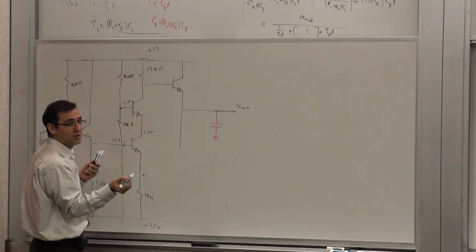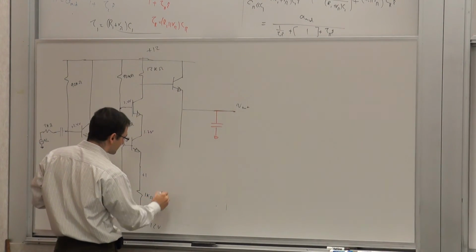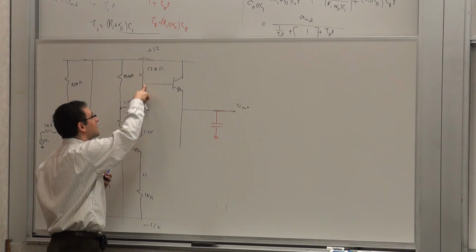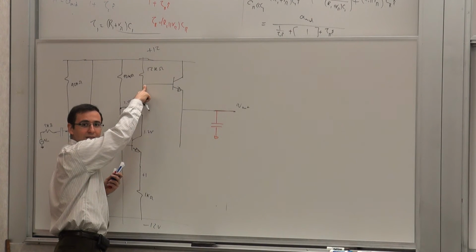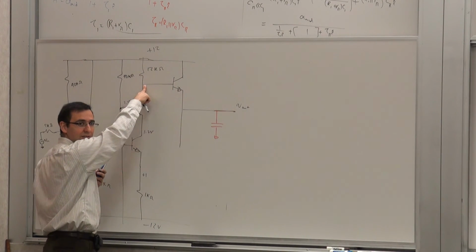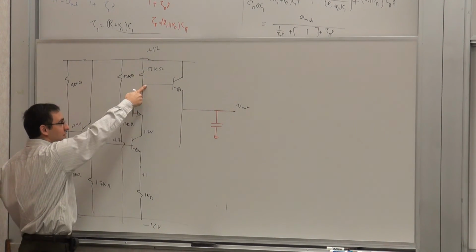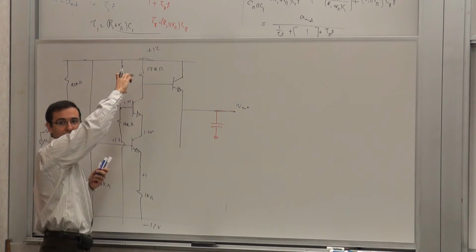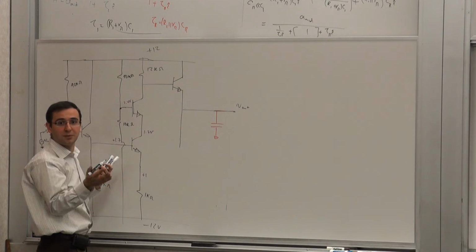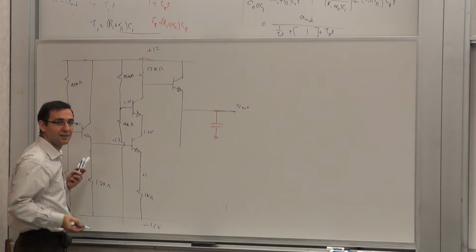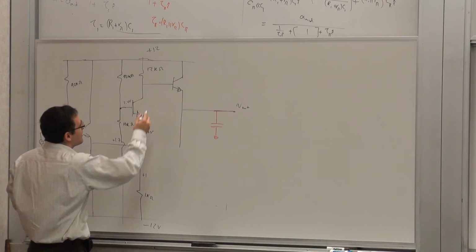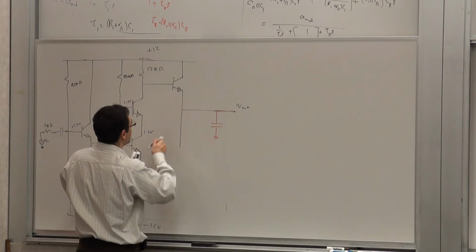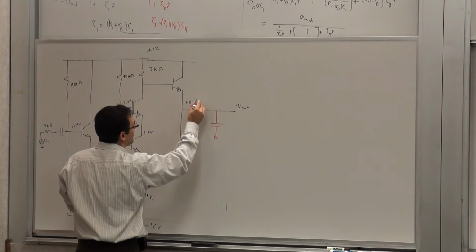By the way, this is something that works if you just put it together on a breadboard. Now, the other thing is, what is this voltage at 1 milliamp? It's 0, right? Because it's 12 volts below plus 12 volts. It's at 0, which is a good place because you want to go both ways. This is where you have your swing. So that's fine. And then I drop 0.7 volts here. So this is going to be plus 11.3 volts.